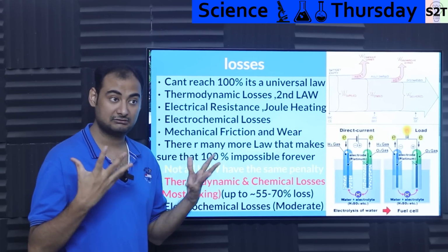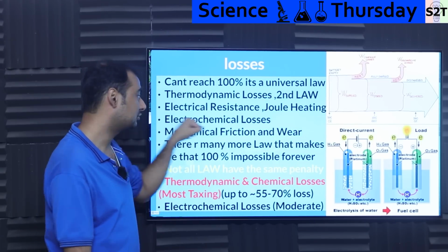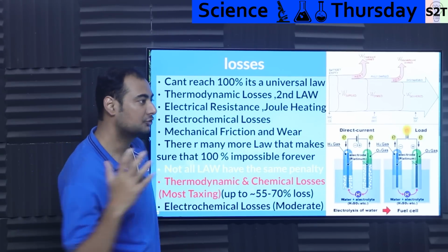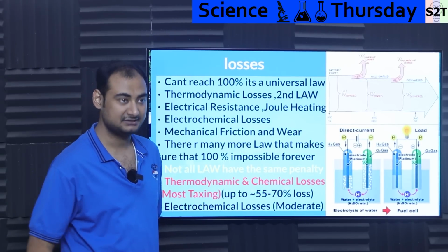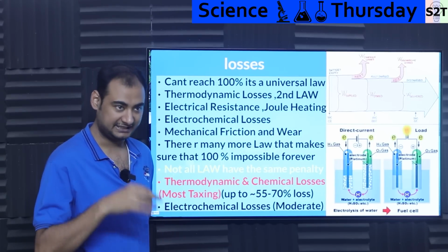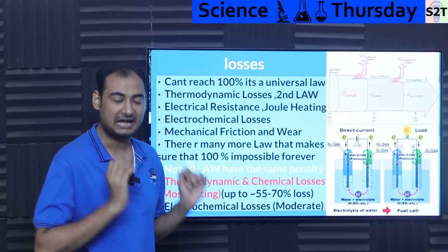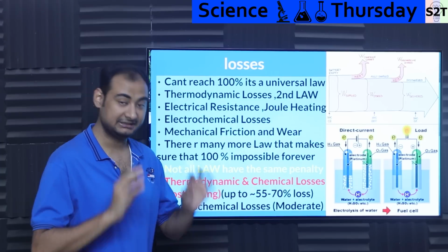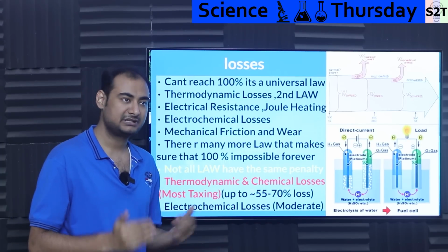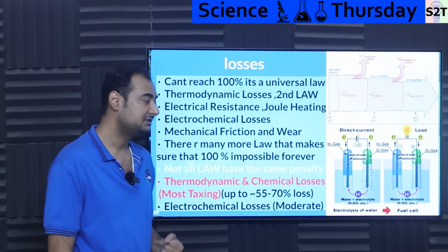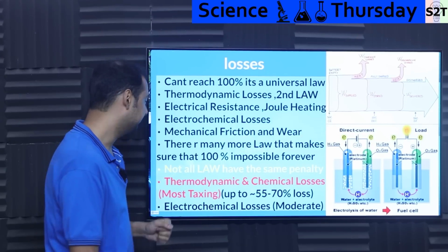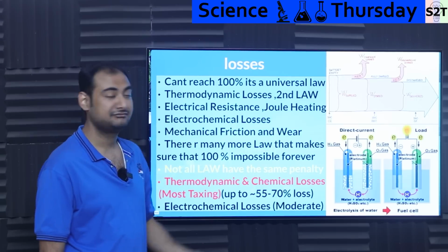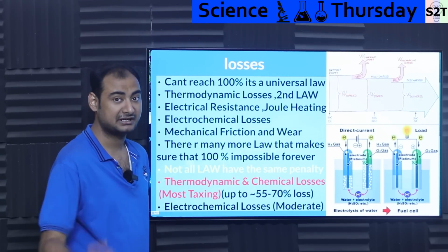And then you have a different layer, the chemical layer, electrochemical losses, meaning every time you say, hey, I'm going to take the lithium ions and force them through something, it takes some energy, and there is going to be a certain loss on the chemical level. You cannot bypass this. You have to waste that energy. The same goes for sodium, the same goes for lead acid. No matter what, there will be certain losses. Some chemistry is really bad, for example lead acid battery. Some chemistry is really good, like lithium. And if you are dealing with a mechanical system, then you will have mechanical friction and wear and tear, so that will also have some penalty.